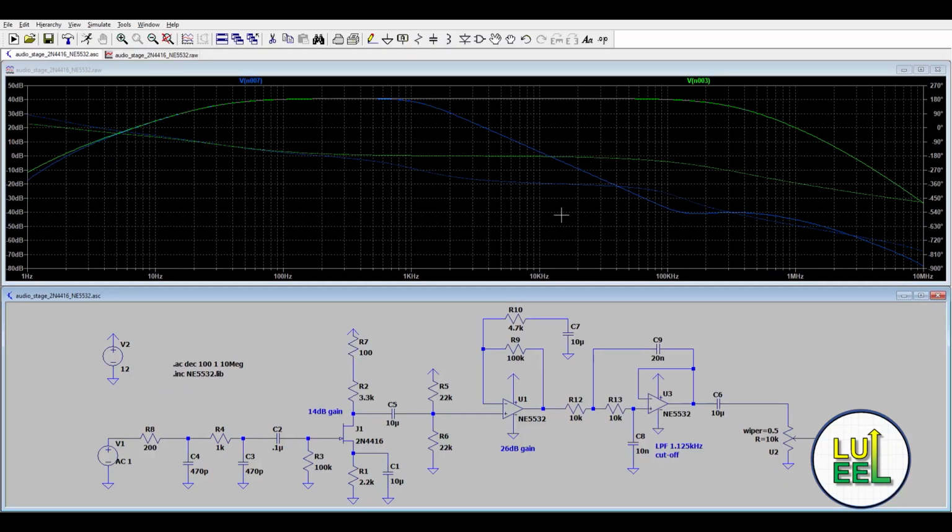One quick item before I talk about progress on the balanced modulator. I decided to alter the design of the low-pass filter on the audio board. If you recall, the design cutoff frequency I chose was around 1.1 kHz, and after some further thought and after reviewing some comparable transmitter designs, I decided that frequency was just too low.